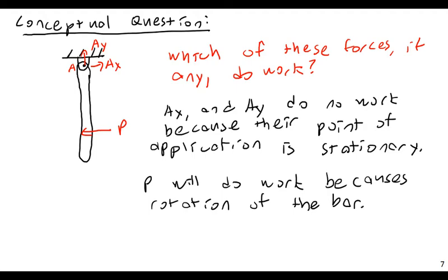Yes, the line of action of the forces passes through the pin. This is another example of constrained motion, which we saw last Tuesday. We are restricting motion to a certain axis or direction, and this thing can only rotate about the pin. So if there is any force that can't cause rotation about this pin, it will cause no rotation.